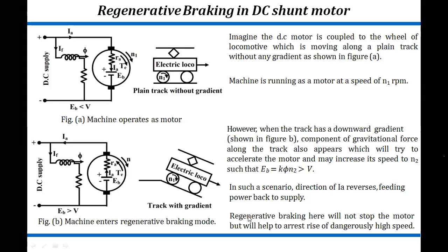So here regenerative braking will not stop the motor, but it will help to arrest the rise of dangerously high speed. It means we cannot directly stop it, but the dangerous, excessively high speed it had, it will allow that speed to come into a safe mode. So it will help to arrest that rising speed to come into a safe limit.